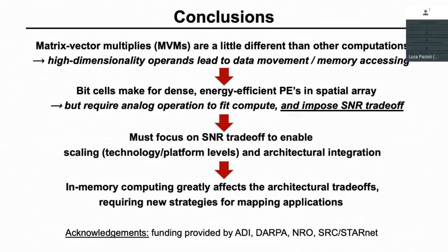Yeah. So remember, each column, I'm doing operations in a bitwise way. So I know what my, for example, most significant bit is. It might correspond to some sort of sign bit, or in 2's complement, some sort of representation of a sign bit. And so once I've done that 1-bit compute on the MSB, I can treat it as a negative number or a positive number in the digital domain when I add it to my other compute in order to do proper 2's complement multiplication and accumulation.